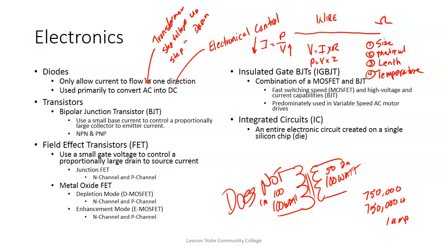And also it induces, so we literally induce a voltage from here into here. So that means motors run off of the repulsion and attraction of magnetic fields. But if I can induce one of them, then we have what we call induction motors, where the magnetic field in the rotor is induced in there. So the big advantage of AC motors is they're cheaper per horsepower than DC motors. The biggest advantage is we can step AC up and step AC down for transmission, and step it down for safety, for us.